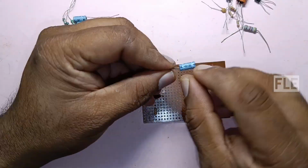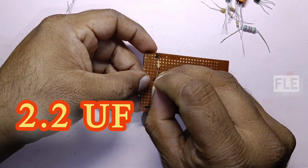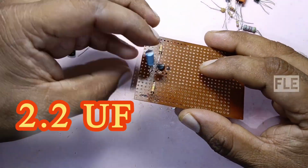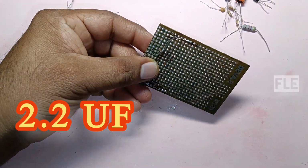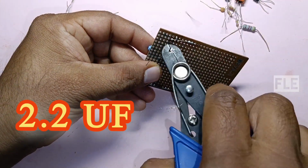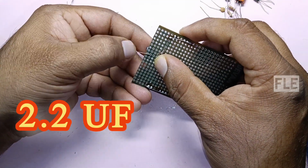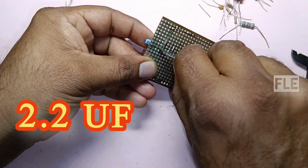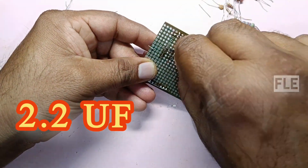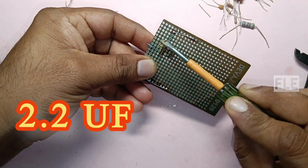Now the 2.2 microfarad capacitor. This is an electrolytic capacitor. The polarity is important. The negative terminal of the 2.2 microfarad is connected to the base and the positive terminal is connected to the 100 ohm resistor.